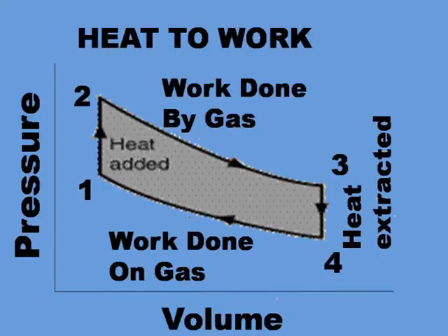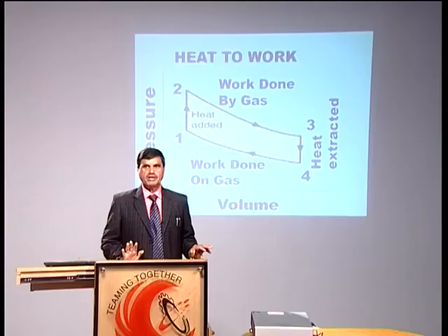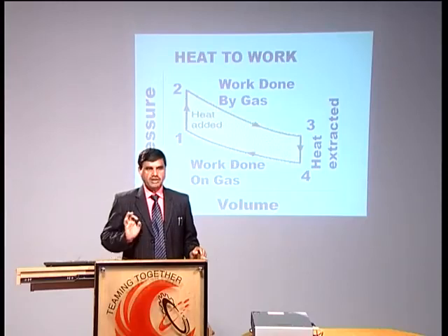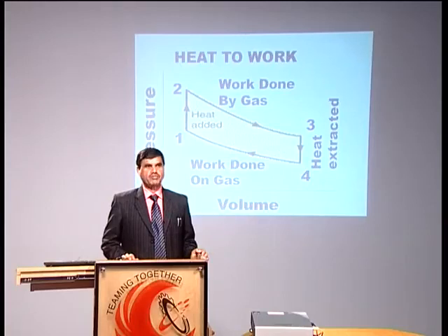When heat rejection to the surrounding takes place, again there is loss of some heat to the surrounding. So, again the efficiency of this type of engine won't be 100%. The compression process from 4 to 1 is a reversible adiabatic process. 2 to 3 and 4 to 1 are reversible, there is no loss, but between 1 and 2, where heat is being added, it is not reversibly added, and 3 to 4, where heat is transferred to the surrounding, is also an irreversible process.